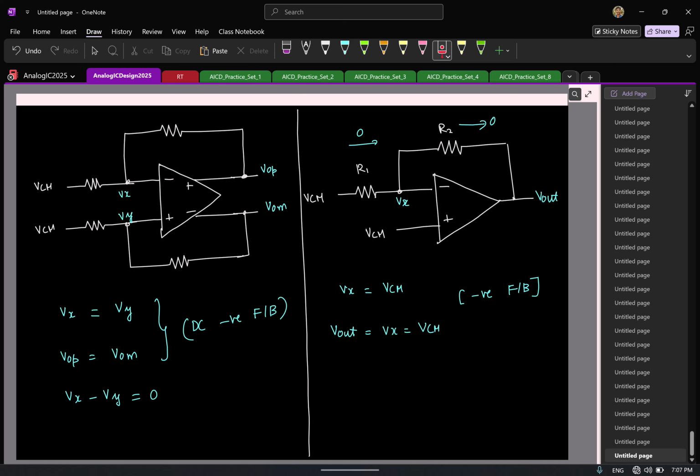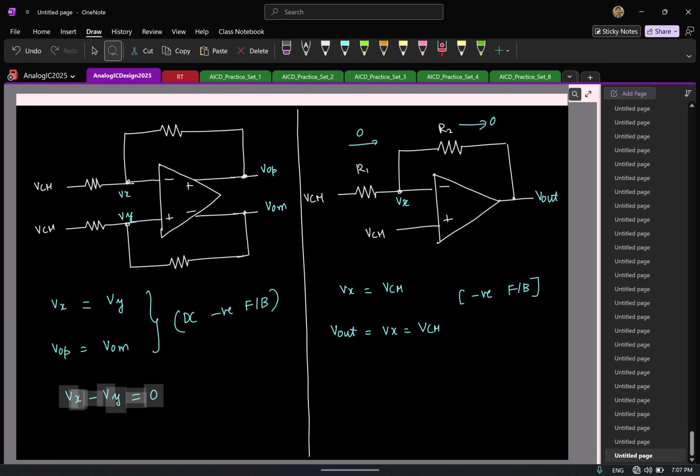I need to define both of them independently, properly. I have one feedback now taking care of the differential part. So, to define the two voltages properly, what should I have now? Is it clear that, if I have this particular structure, my voltages are not defined individually, and what is getting defined is only the differential part?